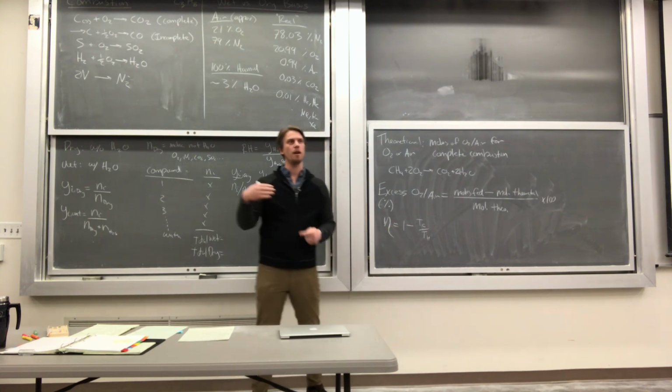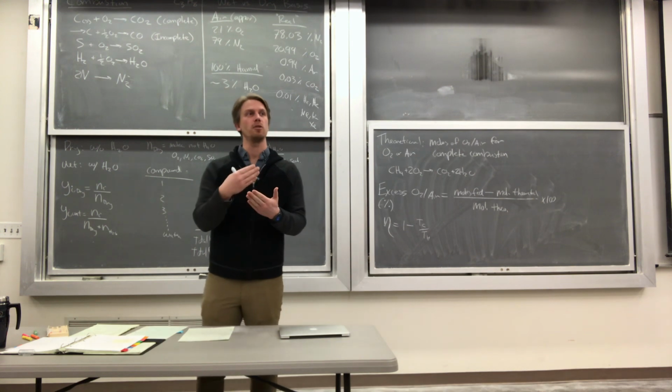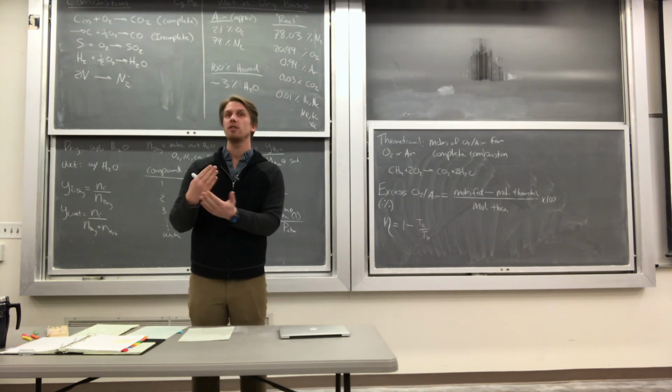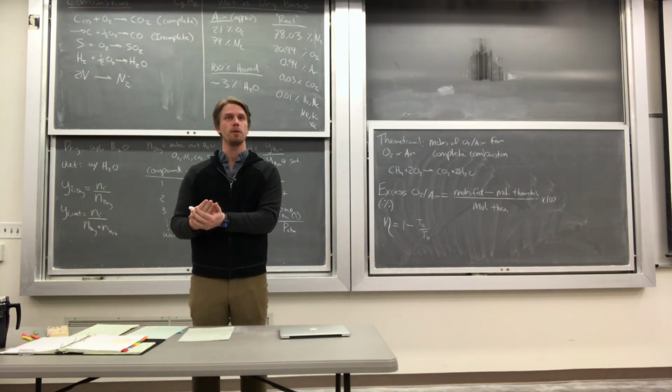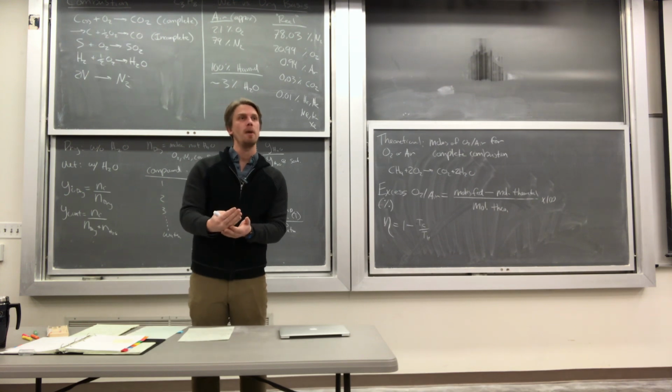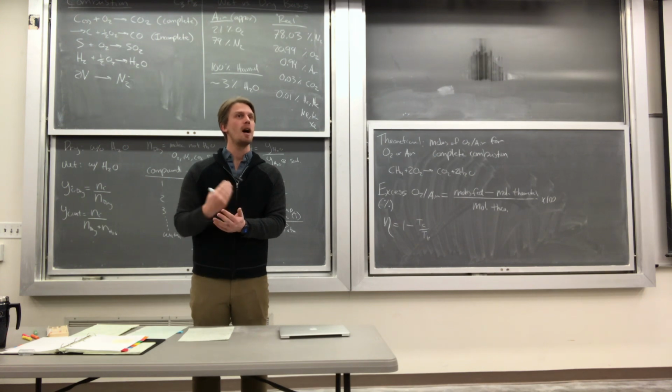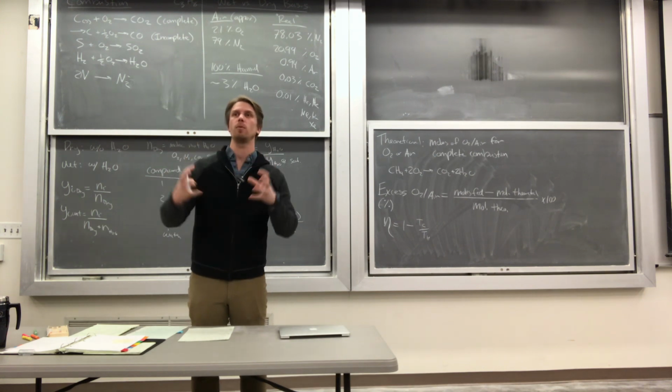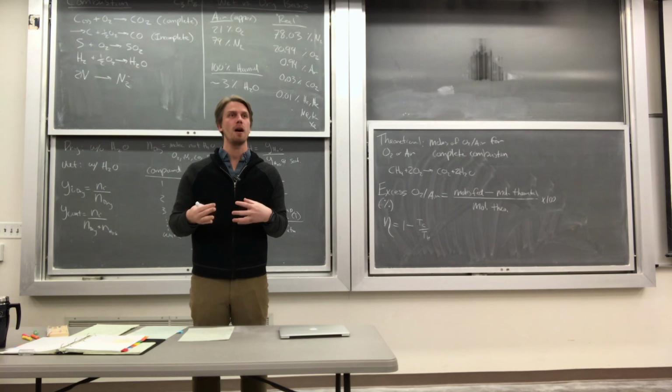So I want to add enough excess oxygen to make sure that I have complete combustion, but not so much that I'm lowering the temperature. Now sometimes we actually need a very, very hot chemical process. Let's say, for example, in concrete manufacturing or making bricks, we need kilns that are hot enough that they can make chemical reactions occur on solid compounds.